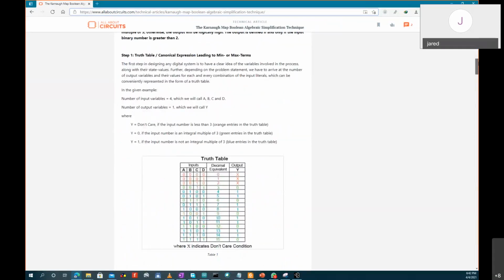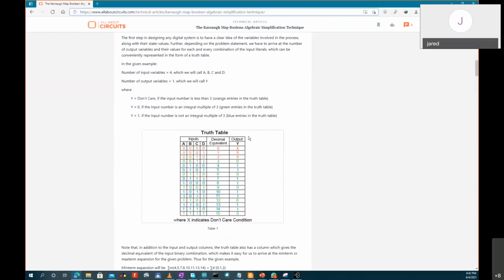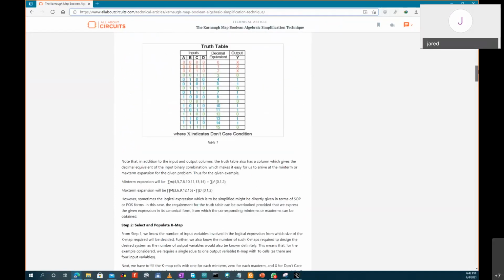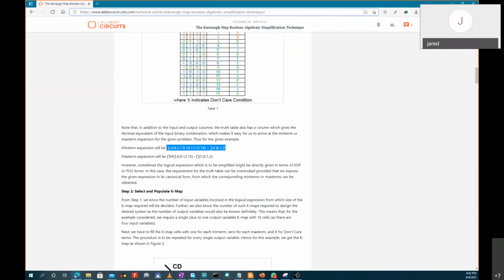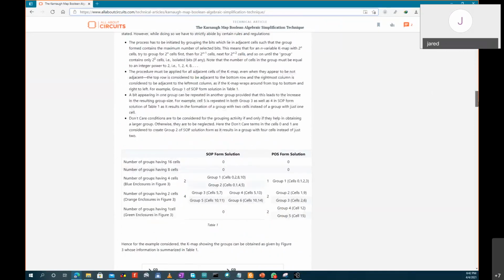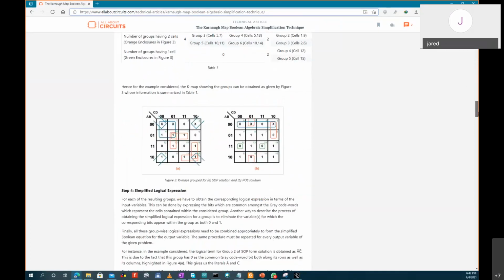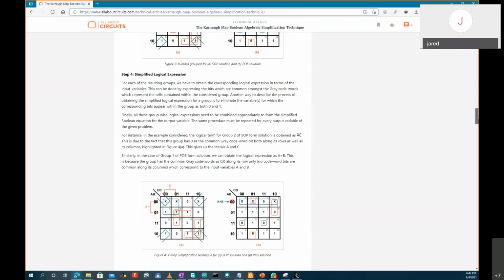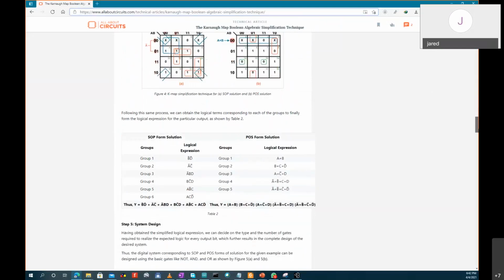You see, like here, it does a combination. So what it does is you say you want the inputs, it will check the equivalent, then it will write for you the simplified logic, the output, and from there you get the min terms and the max terms. I think these are digital electronics things. And once you get the min terms and max terms, you represent them, and from there you can group. It's binary computation, algebra.